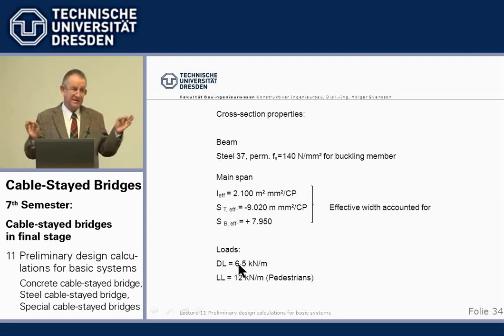We start by choosing a cross-section, like in concrete we do. And then we try to prove that this cross-section is okay. Normally at the first try it's not okay, then we iterate, we make the top flange a little bit more, the bottom flange more, then we do it again. But here we have already a cross-section, I can assure you, which works.